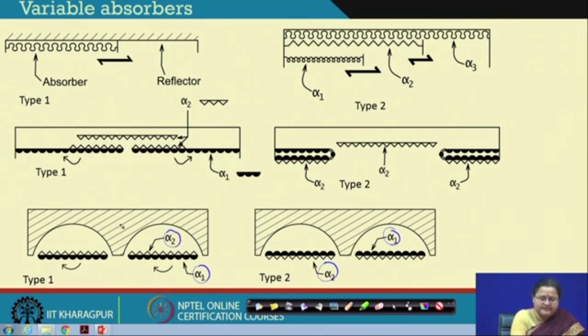So, you have a structural system onto which there is a provision of a circular space where you can rotate the entire thing and have different layers of absorption. So, you see there is air inside it, there is another layer of absorber inside it, and with an exposed different kind of absorber. So, all three members actually behave together to give you a resultant absorption value, and this is obviously keeping in mind the reverberation time.